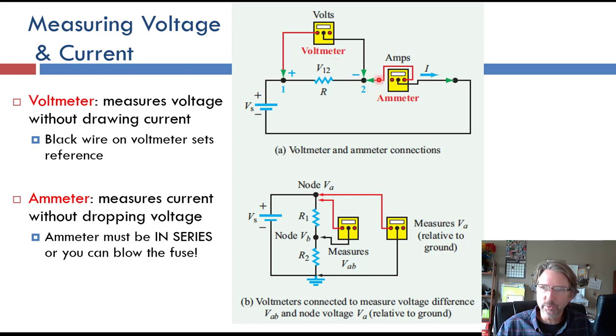So it's important to do these right. This meter has basically zero resistance because we don't want it messing with anything. If you put that straight across this voltage source, thinking you're going to see how many amps are coming out of the voltage source, you'll blow the fuse. There's always a fuse protecting these. You'll get a ton of current flowing through.